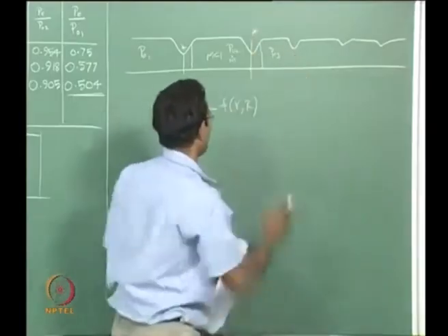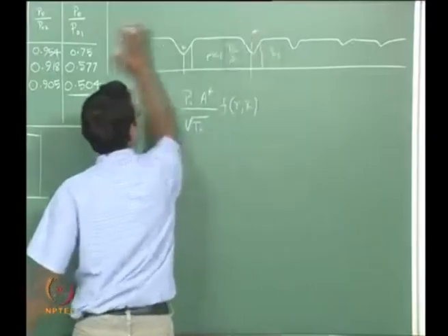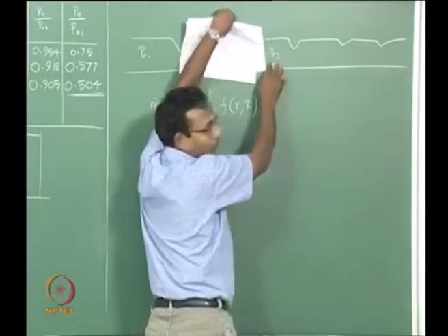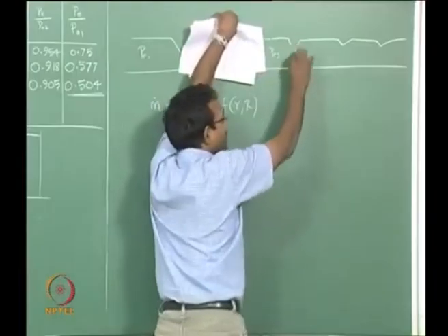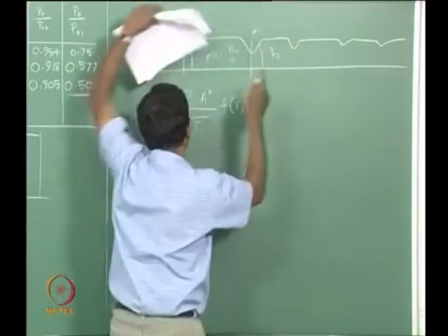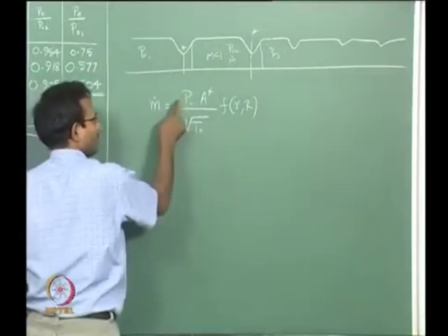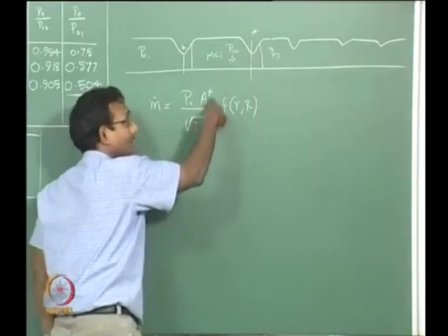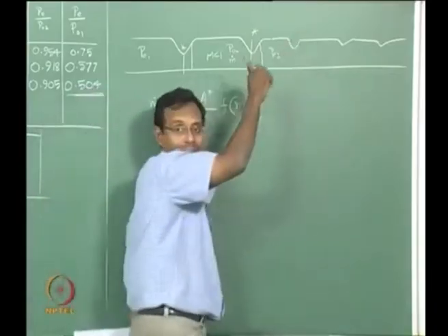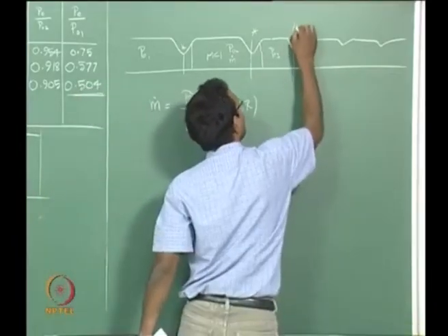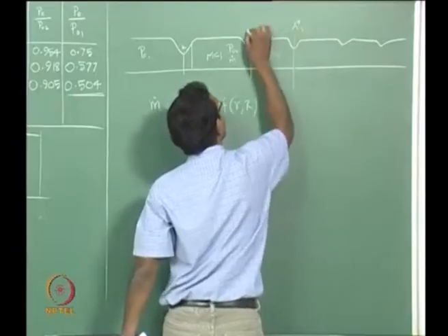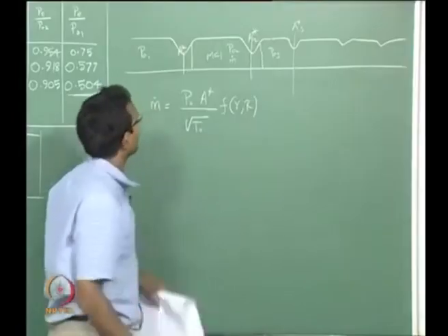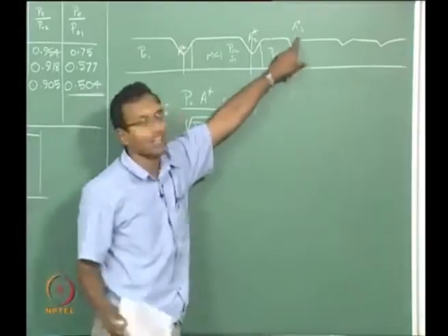I just look at it as a module. All this point is all ignored. Currently I am just going to see this is the only portion that is left. I have a P03 in my duct and I can choke this for a given mass flow rate. I know the mass flow rate, I know the P0, I know the T0, I know the gas, only A star is left. I can now make a new dent, A star 3. Oh, I have to label A stars also, A star 1. So now I can have another A star.